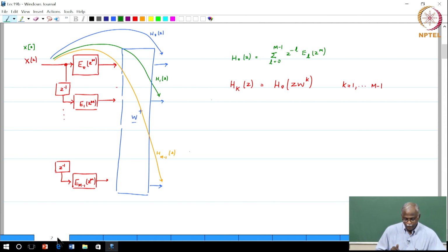The general framework of a DFT filter bank. So keep this as a useful reference point. So this would be a DFT filter bank, and key elements are the fact that we have done the polyphase decomposition and have shown that the inverse DFT is the one that appears here. So we call it the DFT filter bank.